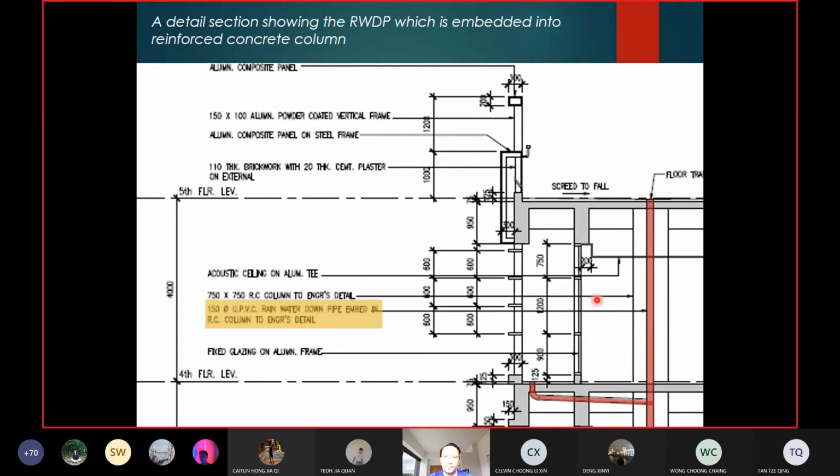It describes everything that you intended for your design. Not like a presentation drawing where you simply design and you don't really have to describe the material. But for a working drawing, yes, you need to provide the specification, the size, the material, the finishes, things like that.